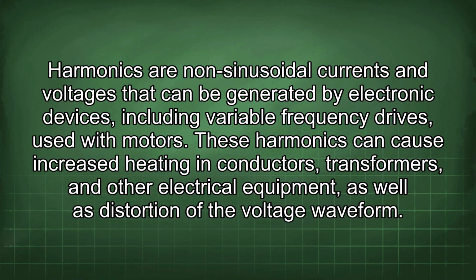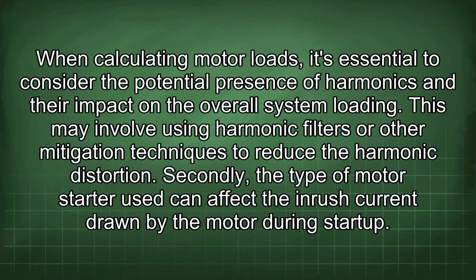These harmonics can cause increased heating in conductors, transformers, and other electrical equipment, as well as distortion of the voltage waveform. When calculating motor loads, it's essential to consider the potential presence of harmonics and their impact on the overall system loading. This may involve using harmonic filters or other mitigation techniques to reduce the harmonic distortion.